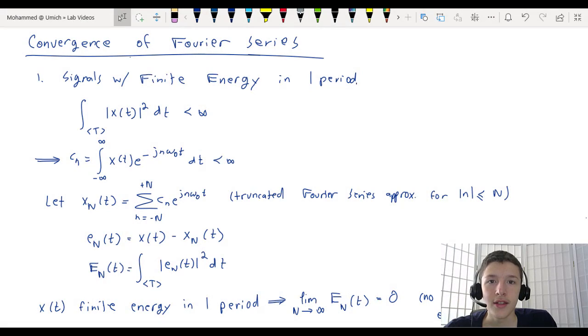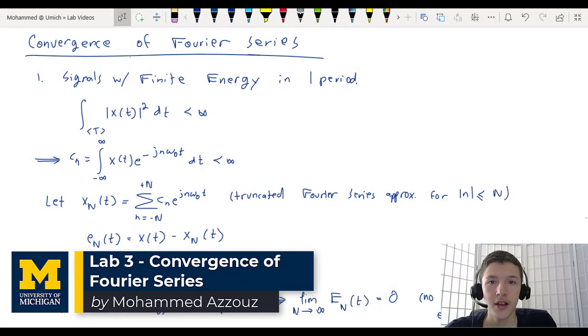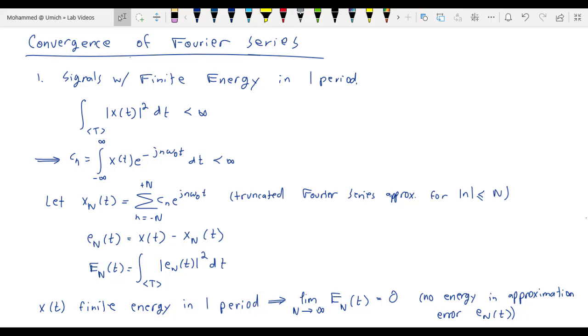Welcome back. In this video, we're going to look at topics related to the convergence of the Fourier series and how this relates to signals with discontinuities like the square wave. Now, Fourier had it that any periodic signal could be represented by a Fourier series. Although this isn't quite true, as we'll see in a little bit, it turns out that the Fourier series can be used to represent an extremely large class of periodic signals, including periodic signals with discontinuities like the square wave, and all other periodic signals that are important in practice.